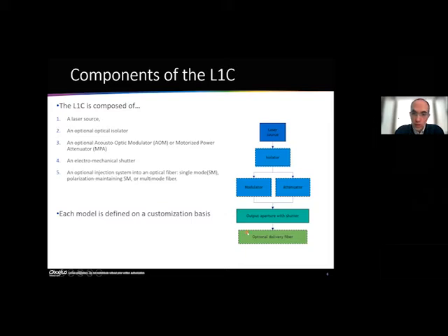And the last option is the delivery into an optical fiber, or as I said, free space. So we can propose either a single mode fiber, a polarization maintaining single mode fiber, or a multimode fiber chosen to fit the wavelengths that are involved.